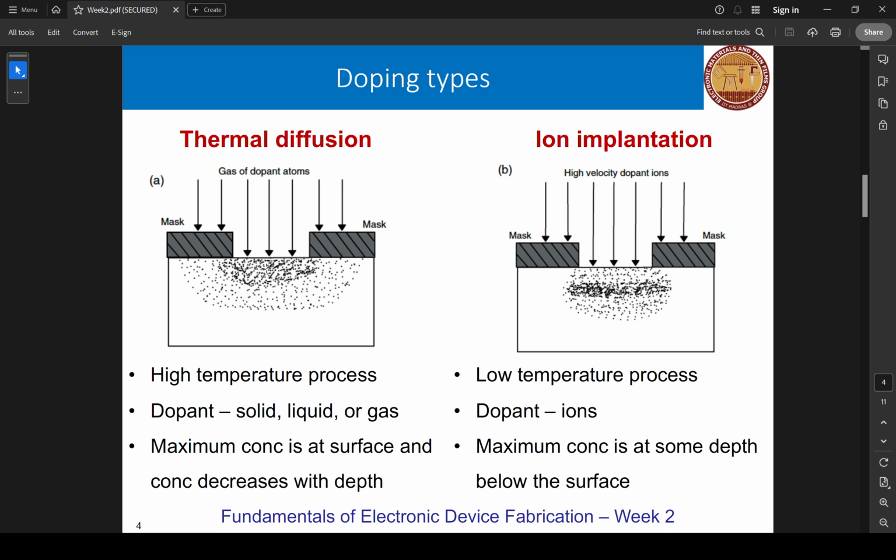But sir, in a video, he tells that arsenic and antimony will predominantly do vacancy diffusion. If vacancies are available, they will go and diffuse there. Yes, they will sit in the vacancies, but vacancies are contributing. Obviously, they are contributing. If they didn't contribute, we wouldn't care about vacancies, right? Vacancies are contributing, but we prefer to have substitution.